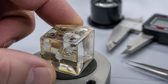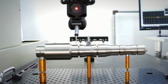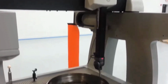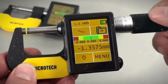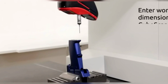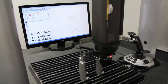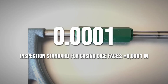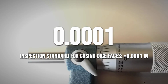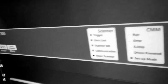Next, the inspector performs a manual evaluation, feeling for tiny burrs or surface blemishes along the sharp razor edges, but human touch only goes so far. To convert qualitative appearance into absolute proof, the inspector places the die under a high-precision digital micrometer and a coordinate measuring machine. These instruments measure each face to confirm the block meets the plus or minus 0.0001 inch dimensional standard. Even a deviation of a single micron, invisible to the human eye, results in immediate rejection.